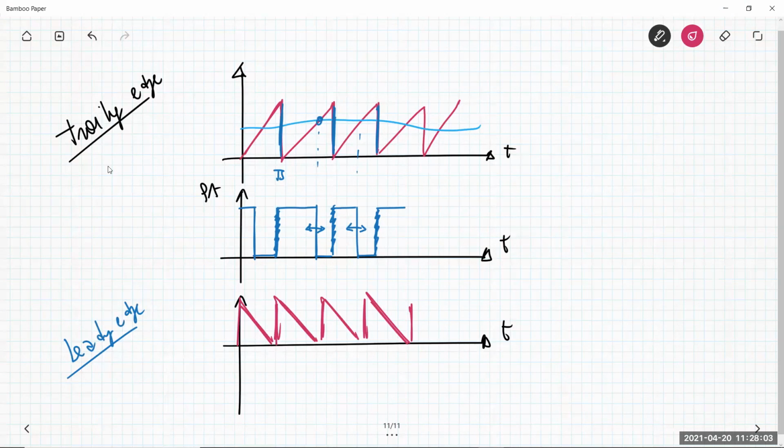The final consideration is that pulse width modulation, the modulation by which I fix Ts and modulate the width of the pulse to modulate Ton, is not the only possible solution. There exist some other modulation techniques. For example, you can keep Ton constant and modulate the frequency. You change the switching frequency, but always have the same Ton. This is also called pulse frequency modulation.